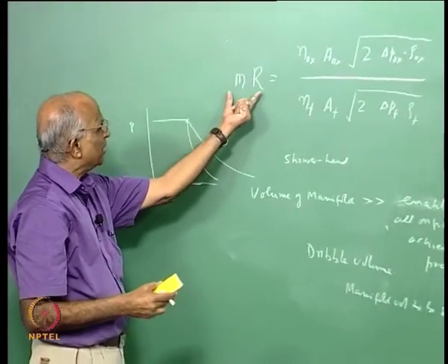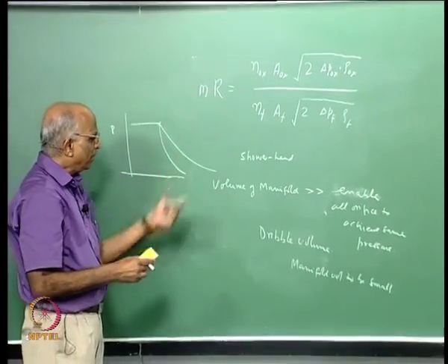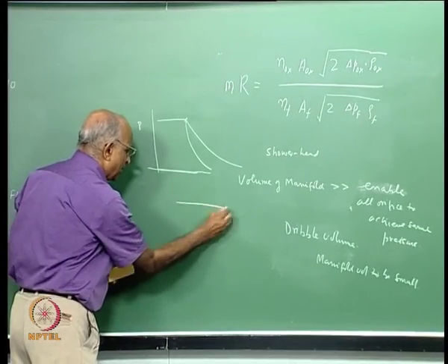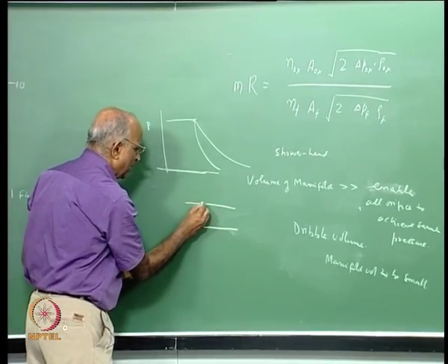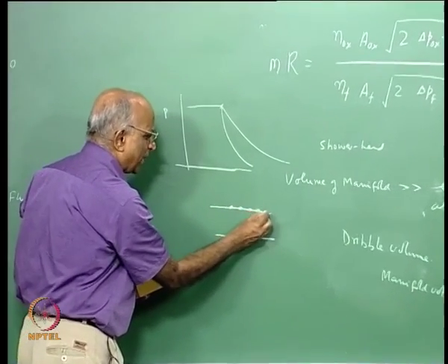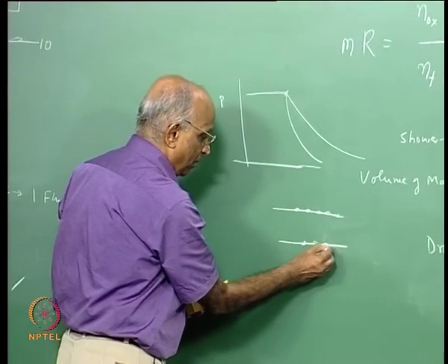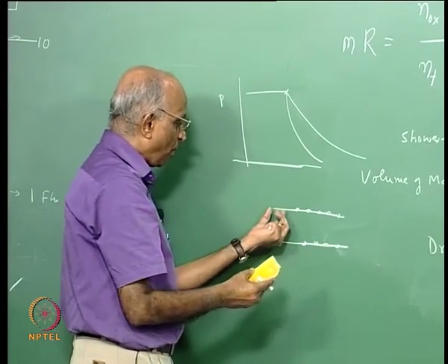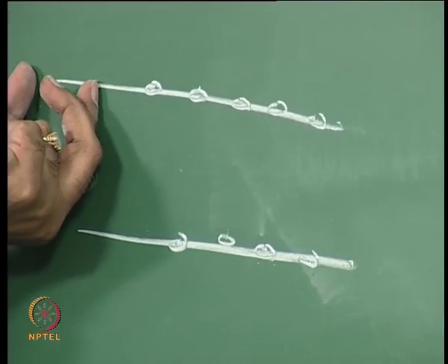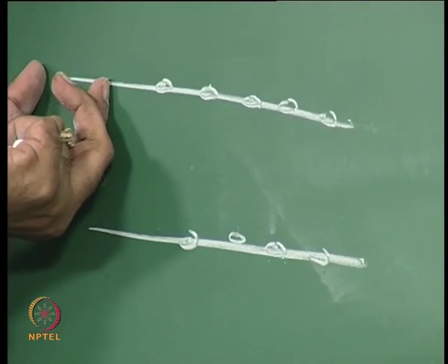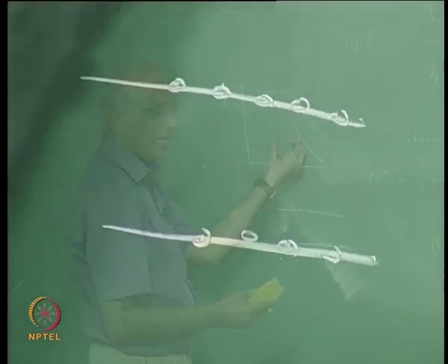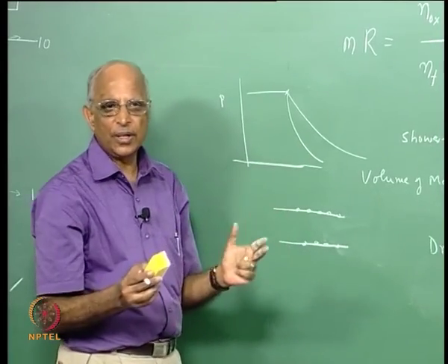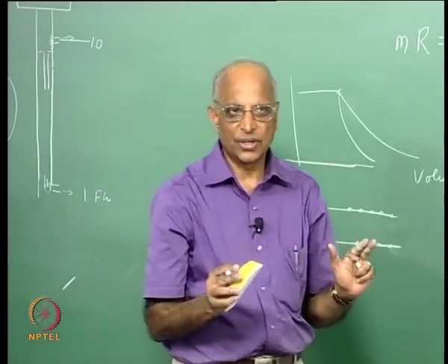But the showerhead injector is something like a weak injector because, as you know, if I have a jet coming like this, it takes some definite time for it to atomize and form droplets, but you want droplets as early as possible. And though some of the earlier designs in liquid propellant rockets used showerhead injectors, at present we never use the showerhead injector.